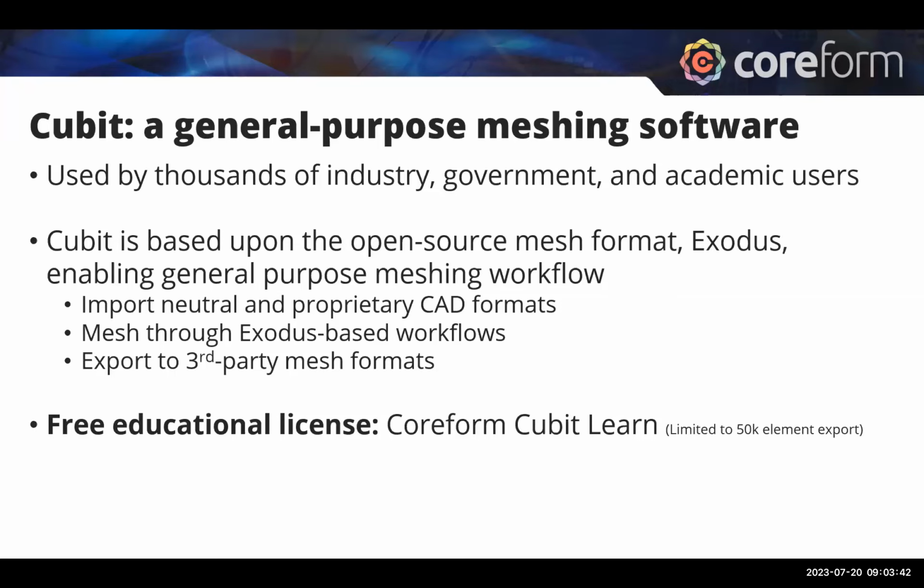Cubit and Coreform Cubit are really based upon the open source mesh format Exodus, which enables some general purpose meshing workflows. We're going to talk a little bit more in detail about the ability for Cubit to import neutral as well as proprietary CAD formats, mesh through this Exodus-based workflow, and then export to third-party mesh formats like Abaqus .inp files, LS-DYNA .k files, and so forth.